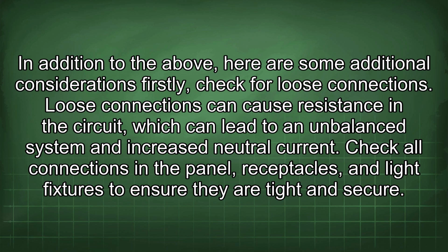Firstly, check for loose connections. Loose connections can cause resistance in the circuit, which can lead to an unbalanced system and increase neutral current. Check all connections in the panel, receptacles, and light fixtures to ensure they are tight and secure.